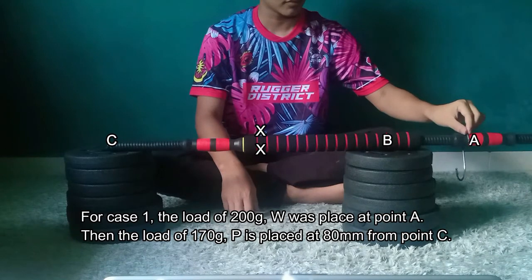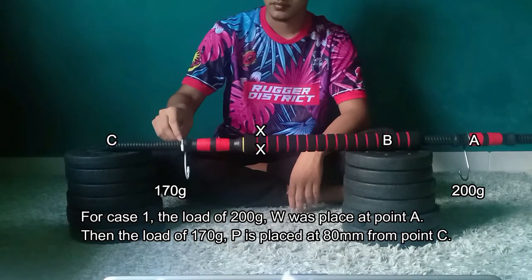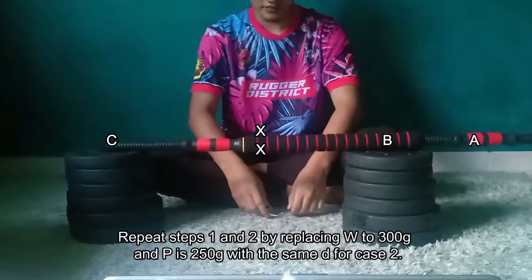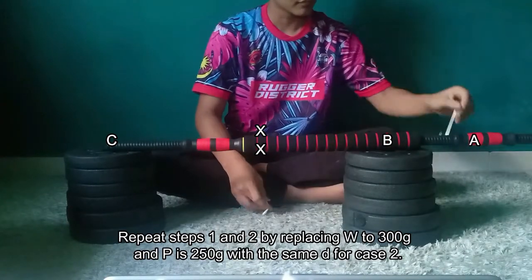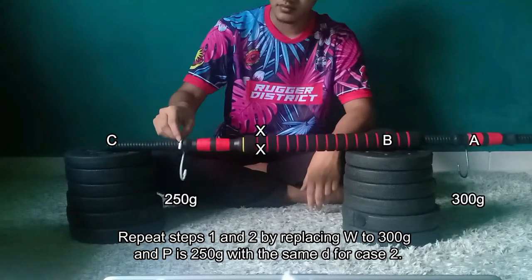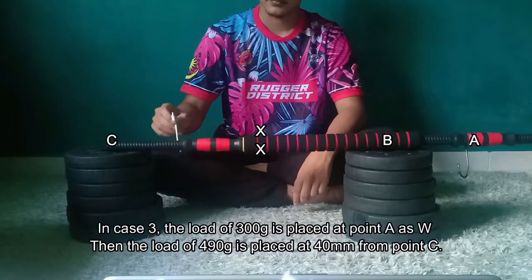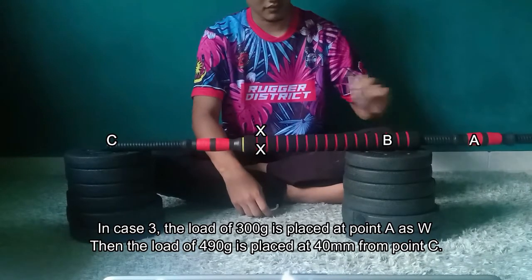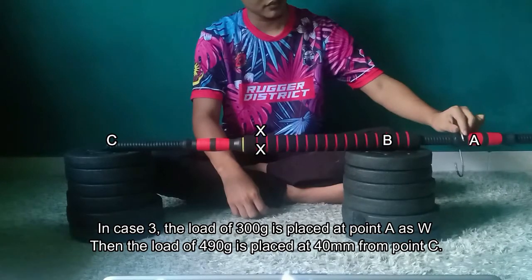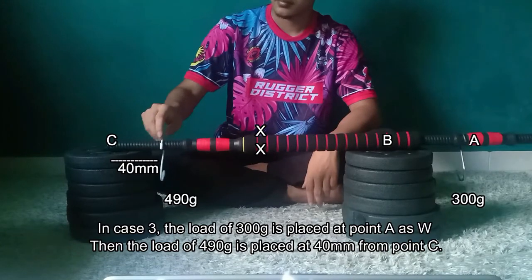For case 1, the load of 200 grams, W, is placed at point A. Then the load of 170 grams, B, is placed at 80 mm from point B. Repeat steps 1 and 2 by replacing W with 300 grams and B with 250 grams with the same distance for case 2. In case 3, the load of 300 grams is placed at point A as W, and the load of 490 grams is placed at 40 mm from point B.